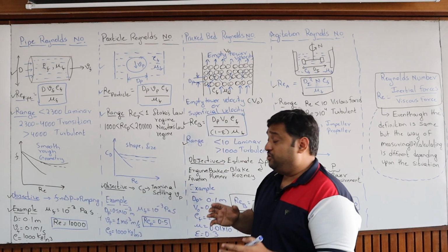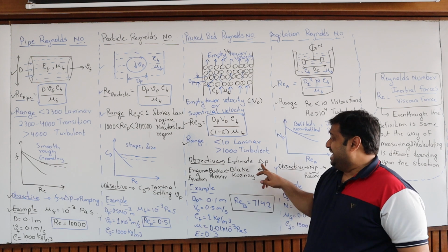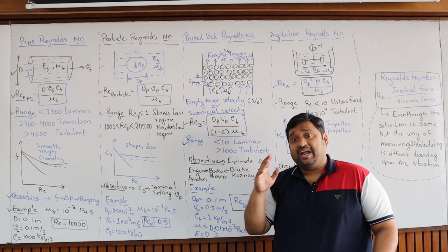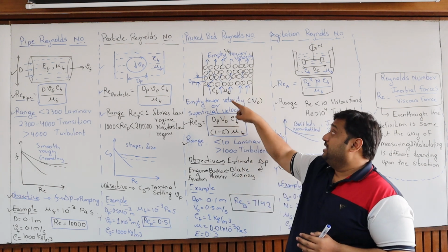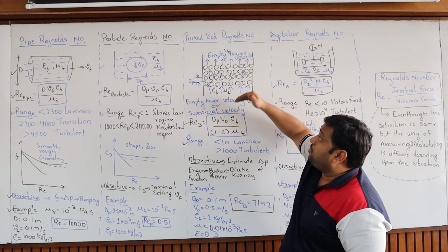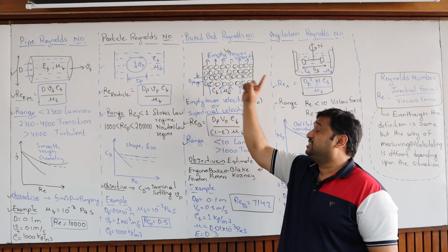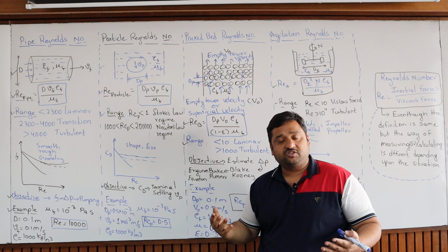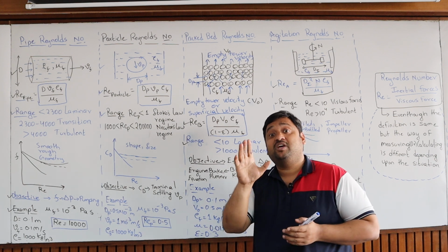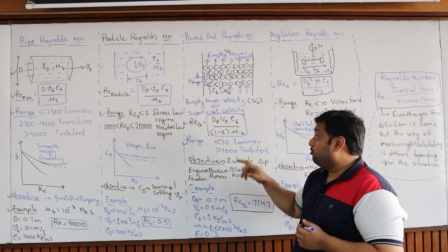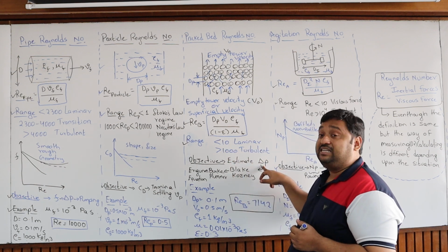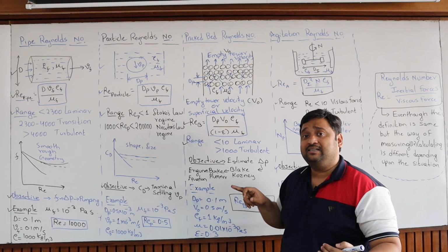Okay, if you ask me what the objective is: if you know the Reynolds number and the kind of regime, the ultimate objective is to estimate how much pressure drop I can expect for this kind of system, because typically in fluidization or filtration chapters you have to estimate the pressure required. Once you know what kind of regime you are in, you can calculate the delta P.